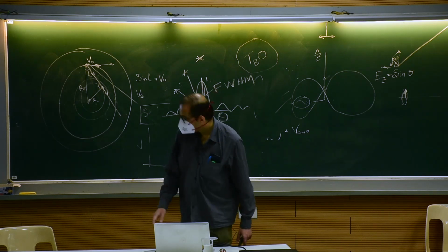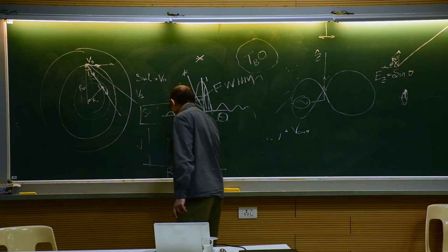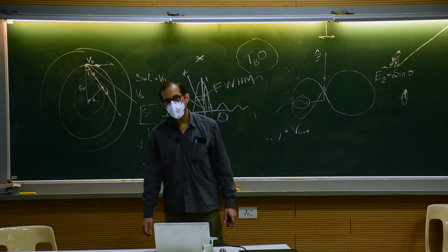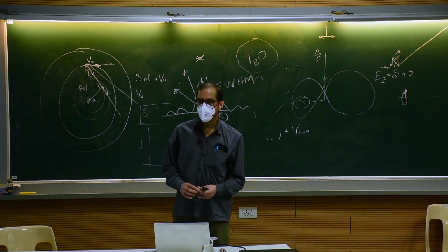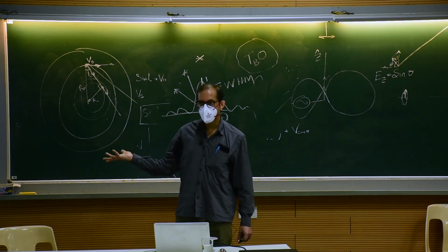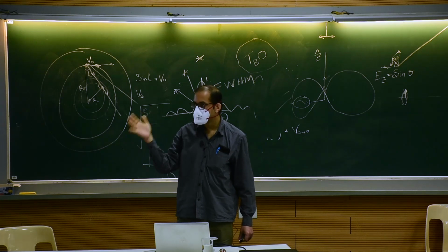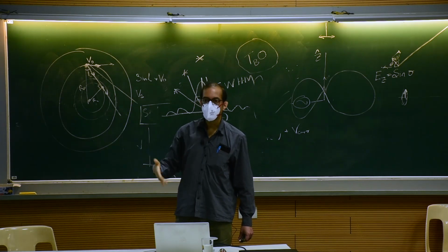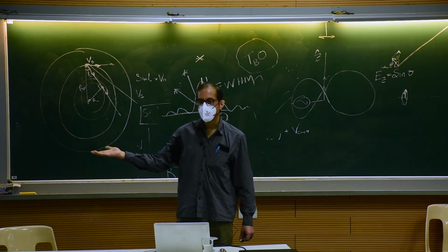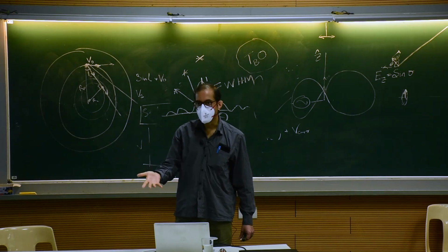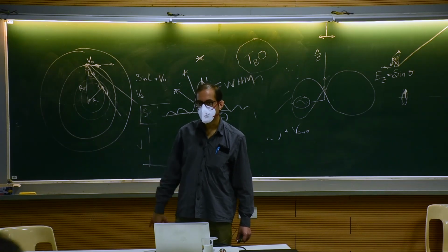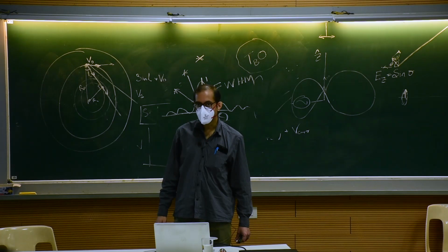The point is, this is something basic and instrumental in nature. Any instrument you use has to be calibrated, right? So it is effectively a calibration procedure. Your instrument is telling you the altitude is 20 degrees, but how do you know it is 20 degrees? It could be 25 degrees. The instrument has wrongly been given a zero which is not the true zero. So this is just the instrumental zero calibration, nothing else. The zeros of the system are not well determined. That's all.